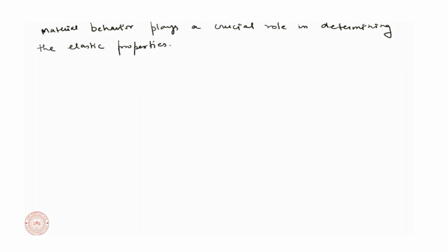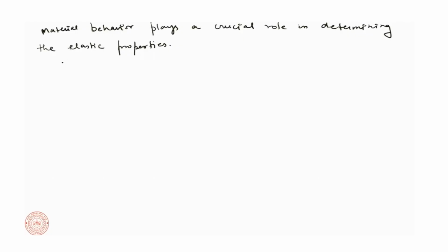Okay, so the constitutive law itself is material driven. These are done by experiments. You do an experiment, you measure the strain for a given applied stress, and based upon that you try to get out these constants. Some materials can have 2 axes of symmetry, some can have 3 axes of symmetry. Based upon the axes of symmetry, you are able to reduce the number of constants that you need, and our C_ijkl, that is our stiffness tensor, or our compliance tensor, likewise can be modified and simplified. So let us take the first type of material.